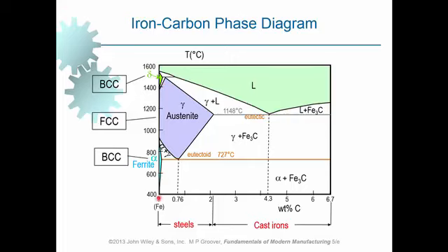Okay, and we know that for pure iron, within this temperature range, starting from room temperature going up to 914 degrees C, what we have got is called ferrite, and the carbon content of ferrite could be up to 0.022% at this temperature, that is 727 degrees C. This line is referred to as the eutectoid isotherm line, and its temperature is 727.